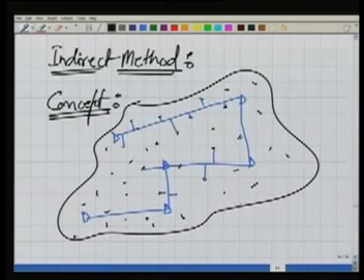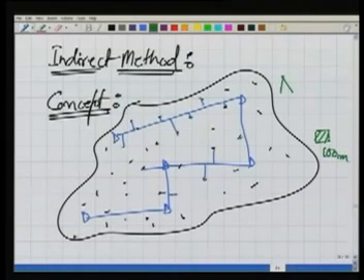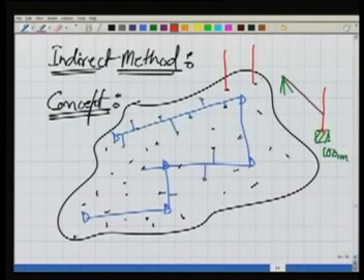Next, for example, let us say by establishing a benchmark here, it is 100 meter for example, also by keeping a level, by taking a backsight on the staff which is kept on the benchmark, then what I can do, I can move my staff to all these points, wherever these points are, and I can start taking intermediate sights.